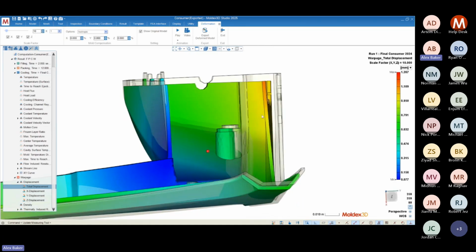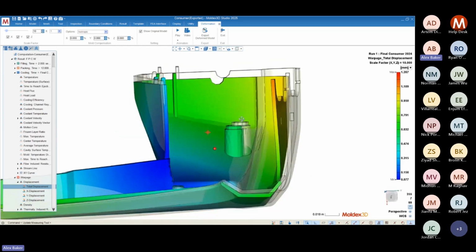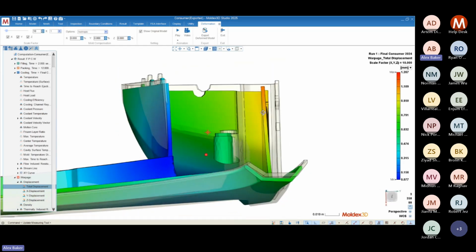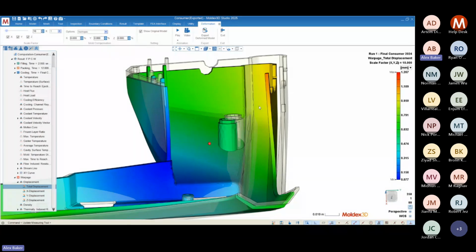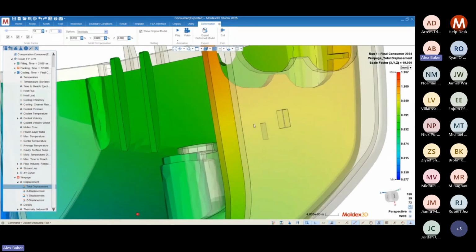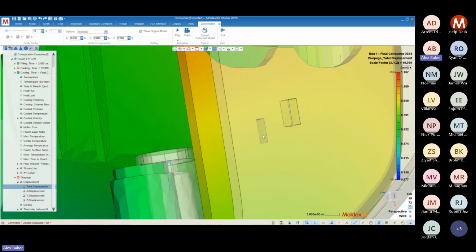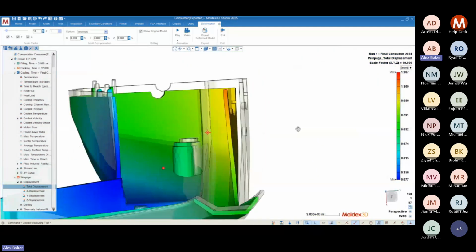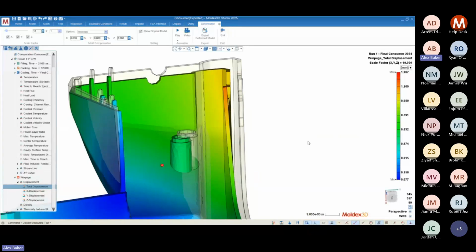And unfortunately for this wall, it's the only one with the degree of freedom to displace in the way that it does. And so we see that wall kind of collapsing inwards. Again, this is 10 times scaled, but this is a good indication of, if I have a tolerance that I need to hit, for example, if this window needs to fit into something, then I can get an idea of what areas of my part are going to be contributing to the part being out of spec.